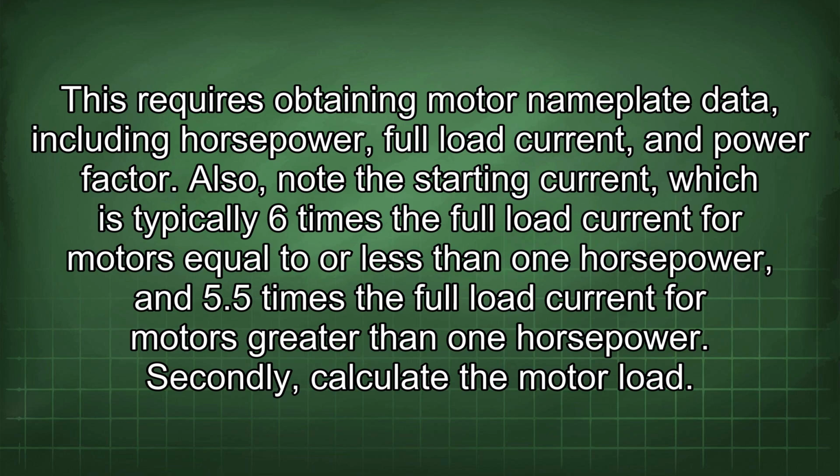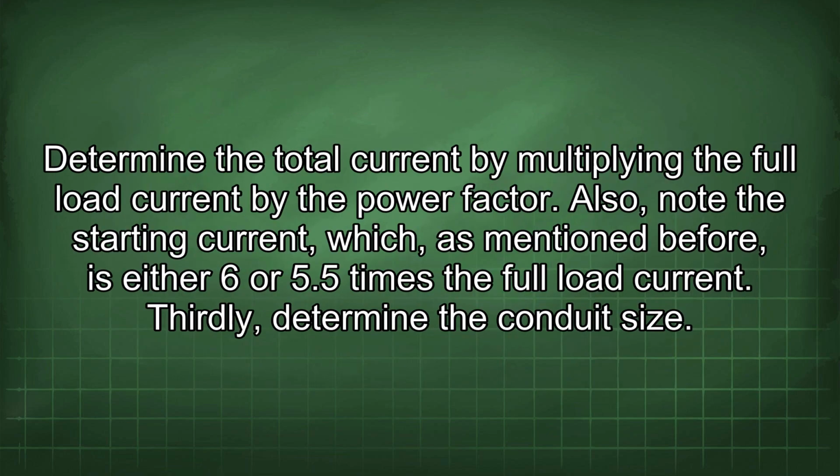Secondly, calculate the motor load. Determine the total current by multiplying the full load current by the power factor. Also, note the starting current, which, as mentioned before, is either 6 or 5.5 times the full load current.